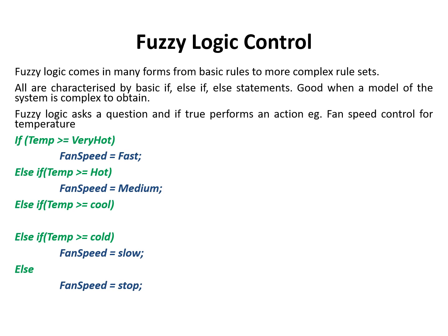So one basic idea would be to write this as a sort of word problem. That's what the fuzzy logic controller basically does: it breaks down the system in terms of rule sets which can be logically based on what you intrinsically believe should be the best approach, or the outcome should be. So for example, if we're measuring an object and we want to cool it down, if the temperature of this object is very hot, then we should set the fan speed to fast. Else, if the temperature is not very hot but it is still quite hot, then the fan speed should be medium.